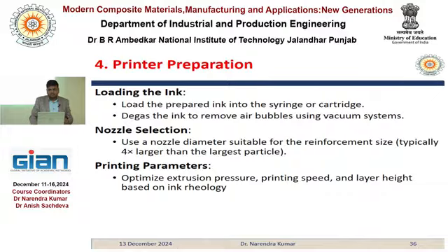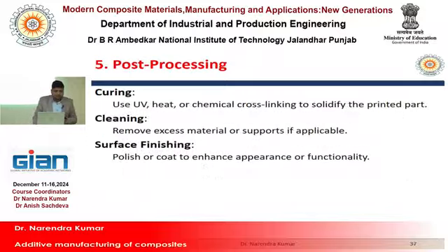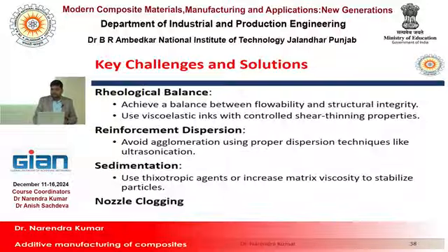Post processing is sometimes required, further curing is required. We can keep the samples in the UV furnace, and then cleaning, surface finishing. So the key challenge is rheological balance. When you are adding reinforcement particles in the resin, balance in the rheology is very important. And sedimentation, again the same problem that was there with SLA. Then nozzle clogging, because here we are depositing material from the nozzle and the nozzle diameter is very small.